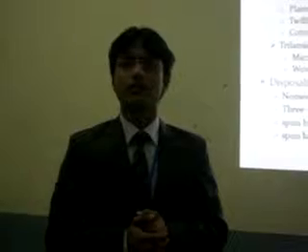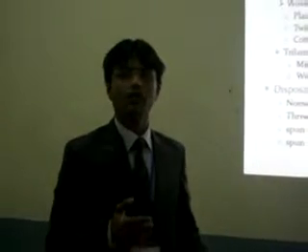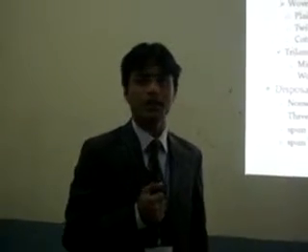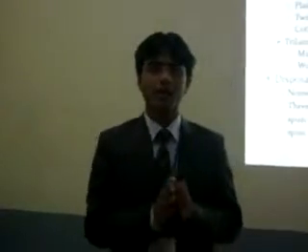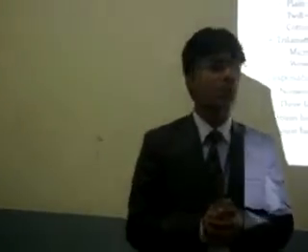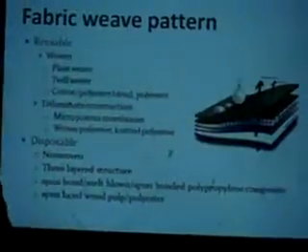In addition, the random orientation provides a filtering media more effective in trapping bacteria and bacteria-carrying particles. The composite non-woven fabrics commonly used in surgical gowns are a three-layer structure of non-woven fabrics combined in a sandwich form. They can be produced from a variety of non-woven fabrics, with the most common being a spunbond melt-blown spunbonded polypropylene composite, and the spunlace wood pulp or polyester.